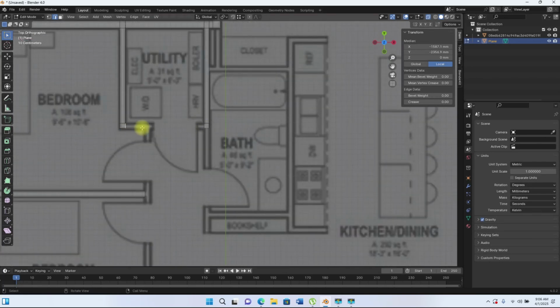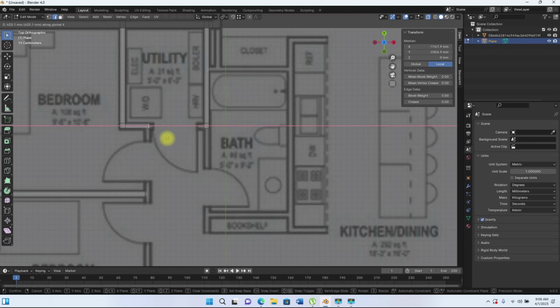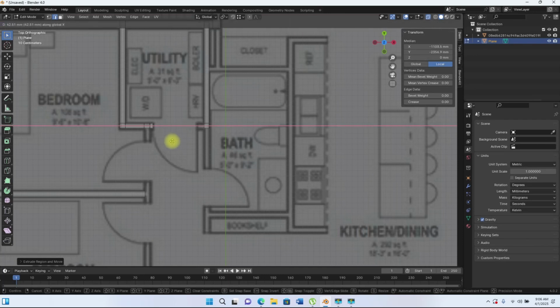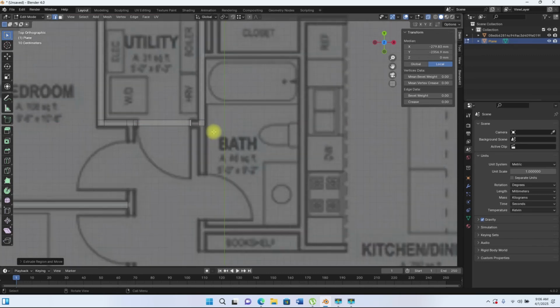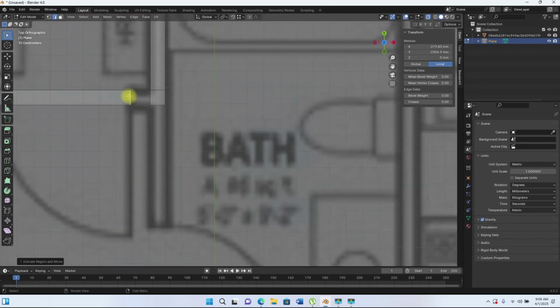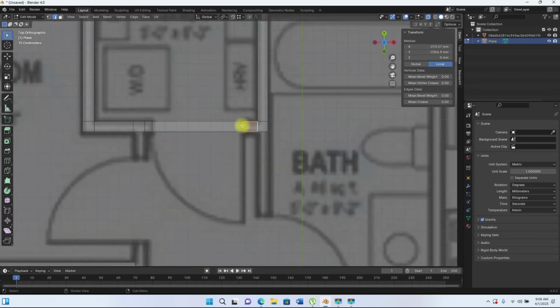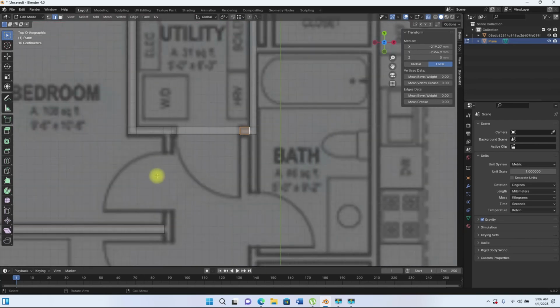So if I come to this place, I can EX to extrude to this point, EX again, EX, extrude to that point, EX to this point. So I'm just getting all of this out. So by the time I'm trying to export everything, it'll be nice. So while I have this and this, you can use F to fill that point. All right. So that's another way you can do that. So F will just fill the edge and then you have that.